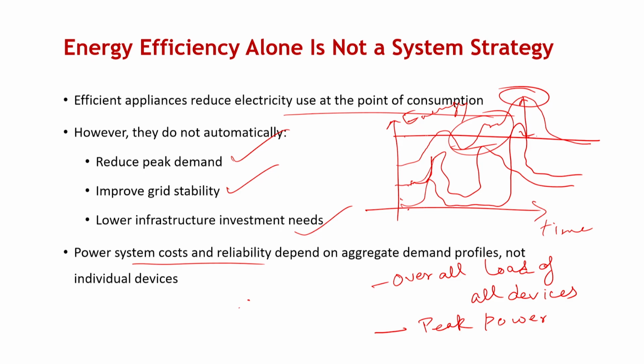And through energy efficiency measures, what I am doing is reducing my energy demand overall. So my overall energy demand has reduced, but have I reduced my peak? If I have not reduced my peak, the chances of a load cut or shed cut can even be higher. So this complicates the situation: if I am not wary of the fact that my demand can vary during the day and with seasons, I need to be careful about that.